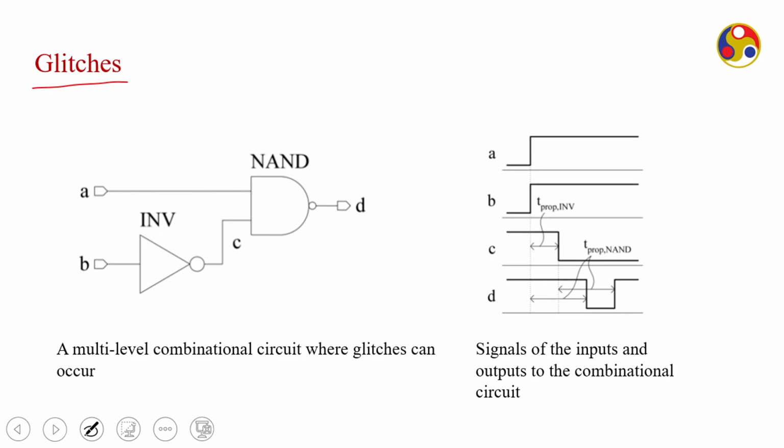In the hardware, you know glitch, what is glitch? Everybody knows it? It is basically, suppose there is an AND gate here, right. Two values are coming. Ideally, if it is 1 and 1, the value should be 1, right. But say this path is longer than this. So, this one comes a little bit late. So, for a moment of time there will be 0, and then there will be 1, right. So, this is glitch.